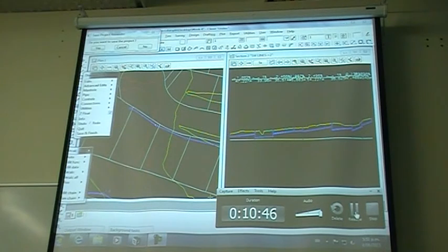So we have to identify where the low points are on each of the sections, and then think our way through the design and layout process for our pipe reticulation to make sure we can pick up those areas.